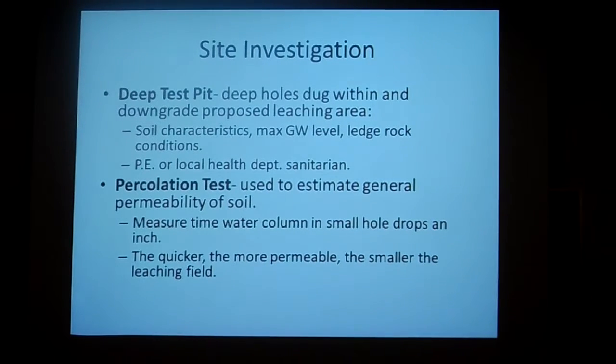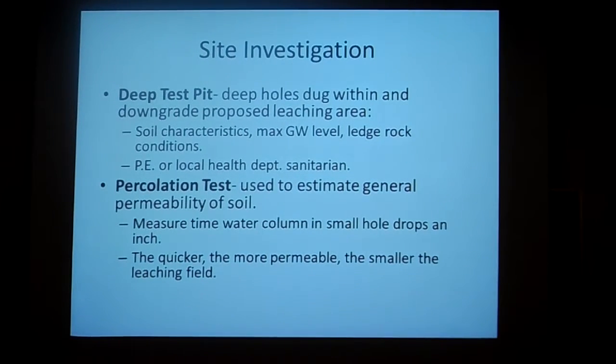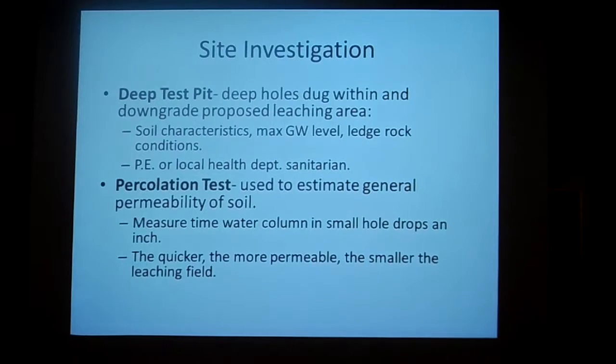A site investigation has to be done before these systems can be permitted, designed, and constructed. You need to do a deep test pit, which is digging a deep hole within and downgrade of the proposed leaching area so that you can observe the soil characteristics, the max groundwater level, and the ledge rock conditions. You also need a professional engineer or local health department sanitarian present. You would also need to complete a percolation test, which is used to estimate the general permeability of the soil.